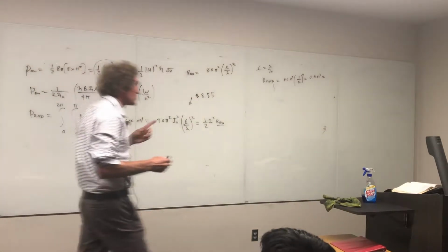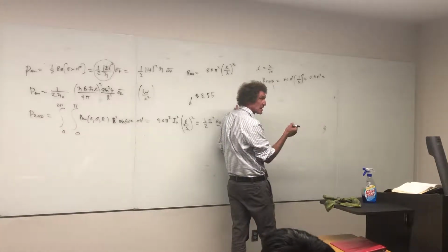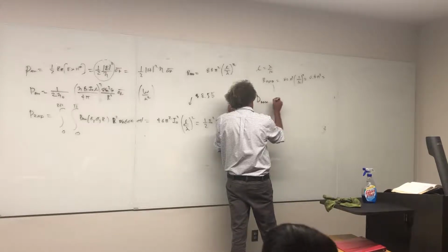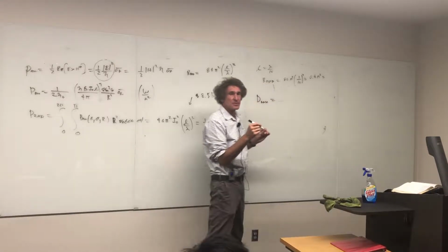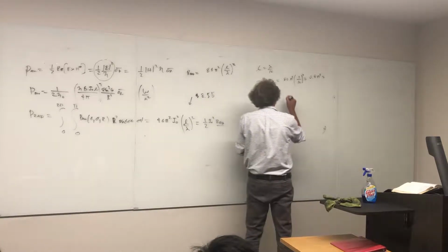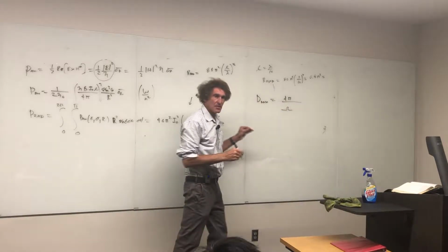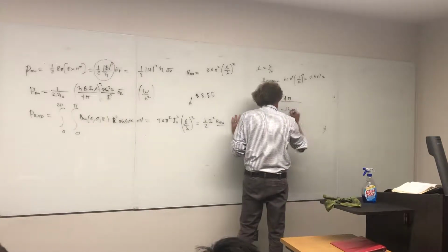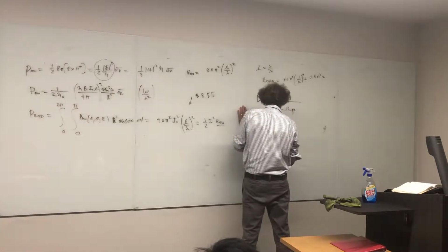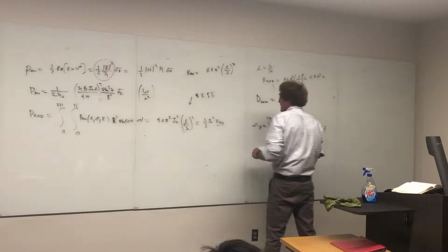One other thing we did about this: first we got directivity, and if we knew the efficiency, then we could get the gain. For the directivity, do you remember how we got directivity max? Make sure everybody's got that. Anybody? Very good. 4 pi, right? And it's over something called the solid angle. In Dr. Whitmore's book, he uses the solid angle. And that is of the form of a double integral, right? From 0 to 2 pi, from 0 to pi, of the normalized power density.